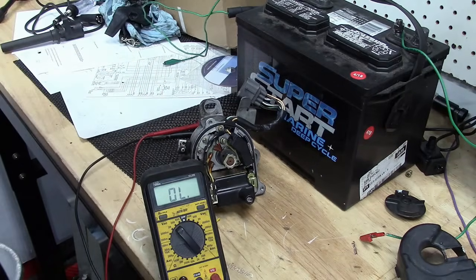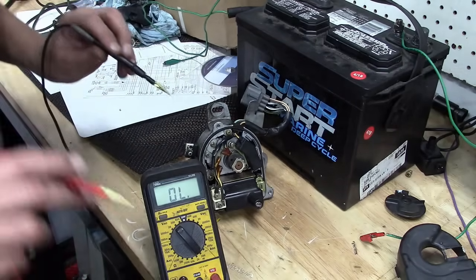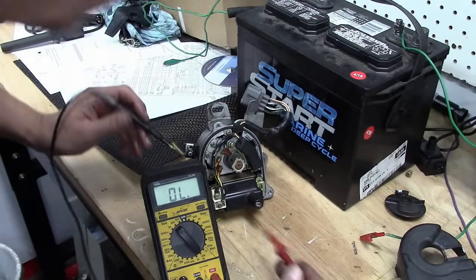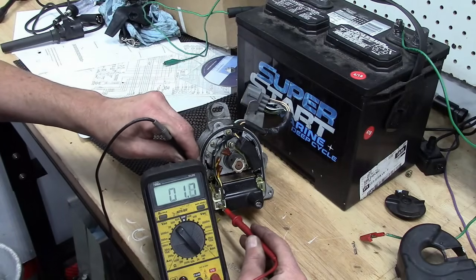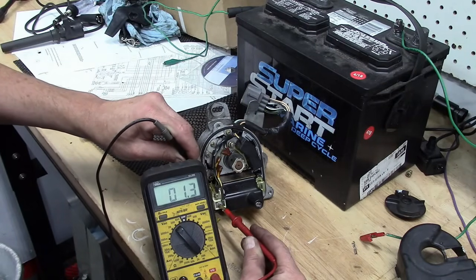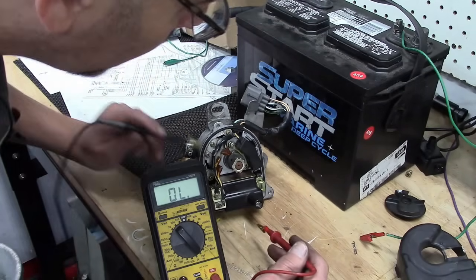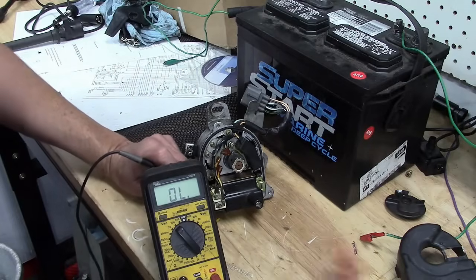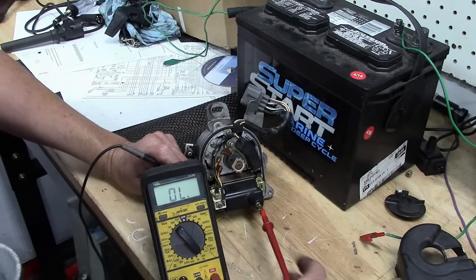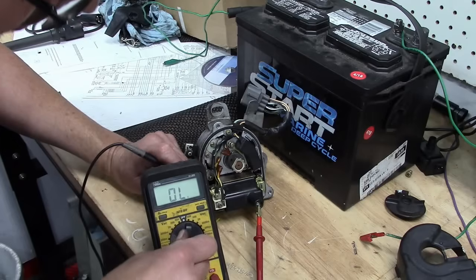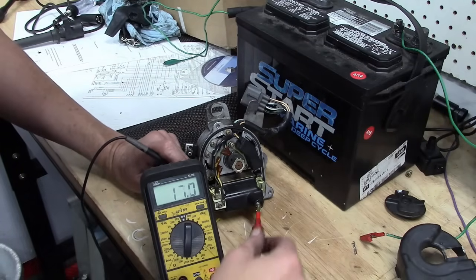So there are a couple of ways of testing the coil. With the coil test, we should have continuity on the primary windings here. So if we test here and here, we see we do have continuity. It should be about an ohm or so, very, very low resistance on that primary winding. I may be wrong about this, so this may not be a valid test, but I think we should have continuity to the secondary here, and that's going to be really, really high resistance, so we need to crank our meter up. And yeah, we do have very high resistance there, probably like 17,000 ohms or so.